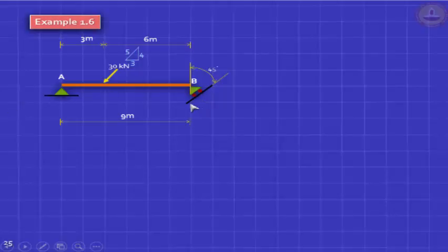Someone turned the roller around like this at 45 degrees to the horizontal and vertical, and to make matters worse, the load is also inclined at a ratio, horizontal 3:4. Obviously, this is to make calculations easy, because if this is 3, this is 4, Pythagoras rule says this is 5. You can give theta, but theta is not needed. This is all that you need.